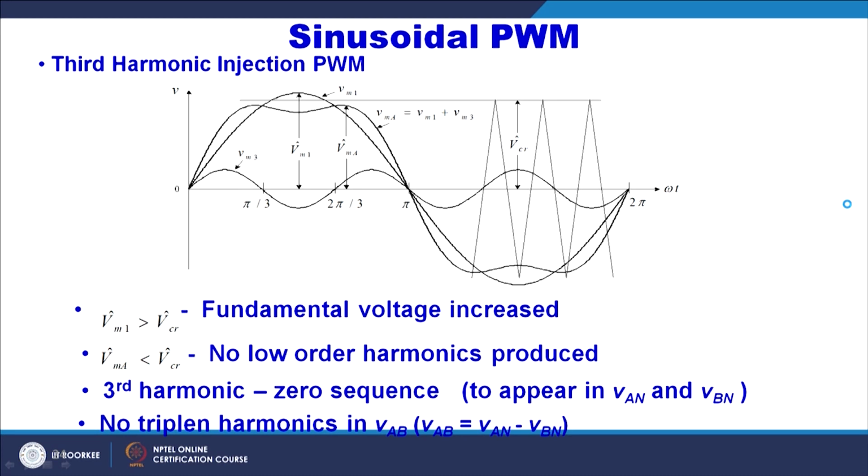For this reason the line voltages will not have any third harmonic. Moreover, you do not connect the midpoint and the neutral point, so they will have infinite impedance for the third harmonics. Thus it will be trapped in the system and will not go out into the line voltages.